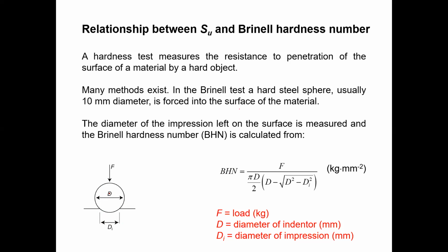Okay, so that means this particular material and this particular material have equal hardness. Like that, if it does not penetrate that much, that means this one is harder than this one. If it penetrates this much inside the material, that means it's very soft. So there is a scale and other things, so you can read the Brinell hardness value.